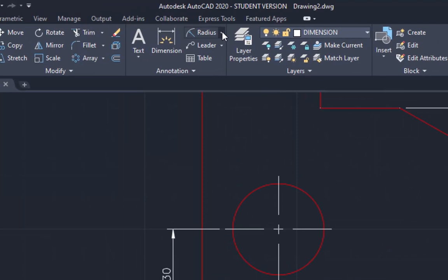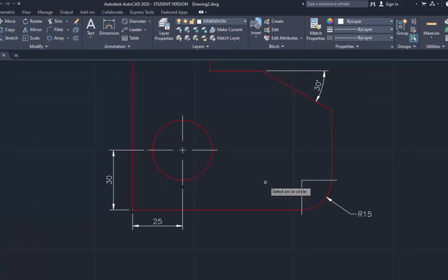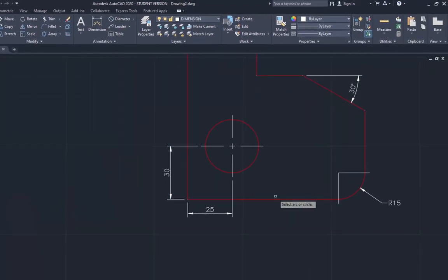If we then have a look at applying a diameter dimension, a diameter dimension is almost always used if it is a hole that you're putting a dimension on, or if it's a machined part or a pin. Those are almost always made, and the equipment used, either a drill bit or a lathe, references diameters, not radiuses.